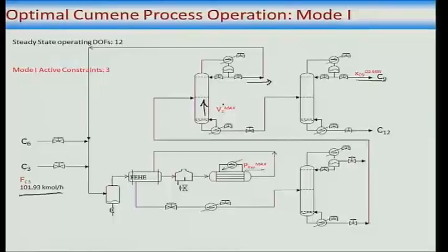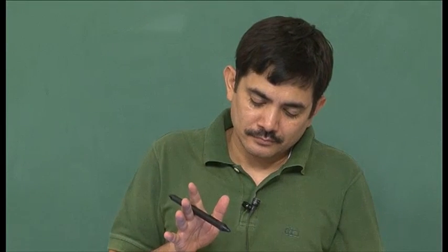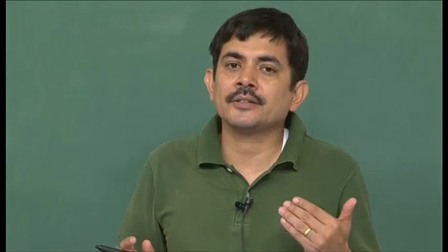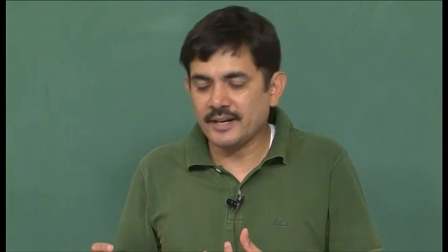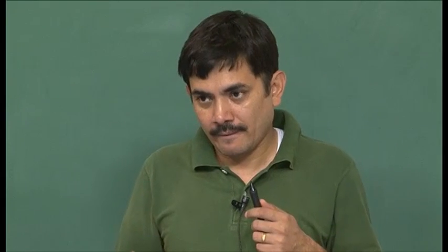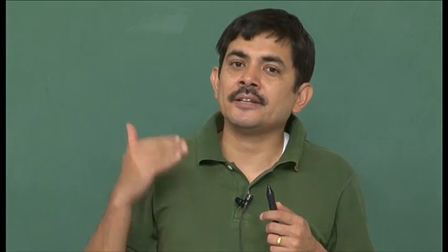So this makes sense. P reactor max is maximum because as you increase the reactor pressure, the rate of the main reaction and the rate of the side reaction go up by the same amount. The ratio of the main reaction rate to the side reaction rate remains the same regardless of pressure. So you get an increase in conversion, but you do not have any selectivity penalty.